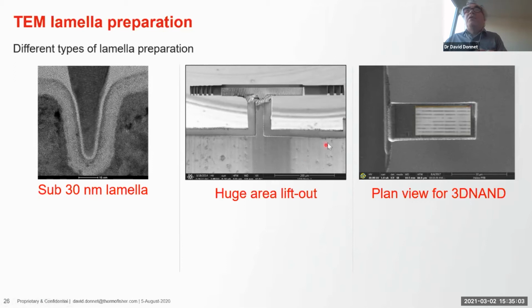What the gallium FIB cannot do is lift out 500 or 600 microns of material. So in this case, we've lifted out about 500 microns. We've attached it to a grid. And then if you can see, we've made windows. So actually we have about 8 TEM lamella on this one sample. So we can get lots of statistics, and we've made maybe 8 samples in around 5 to 6 hours. So it can be very efficient. And this is something that's really not possible in the gallium FIB.